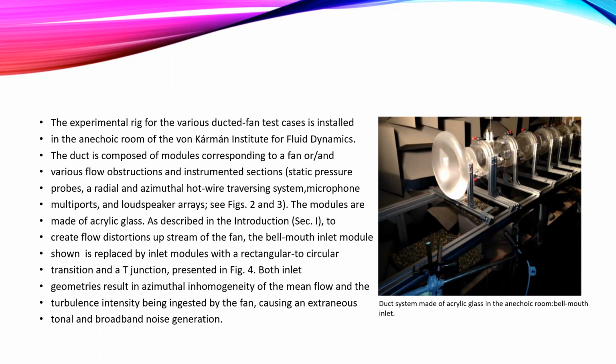This geometry results in azimuthal inhomogeneity of the main flow and the turbulence intensity being ingested by the fan, causing extraneous tonal and broadband noise generation. This is the system made of acrylic glass in the anechoic room with a bell mouth inlet.